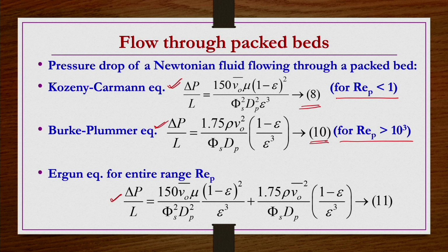Ergun also found that this equation is very suitable for different types of packing materials like spheres, cylinders, crushed materials, etc. He also found that this equation is valid for a wide range of flow rates, from small to large, that is, from small Reynolds number to larger Reynolds number ranges. This equation holds good.